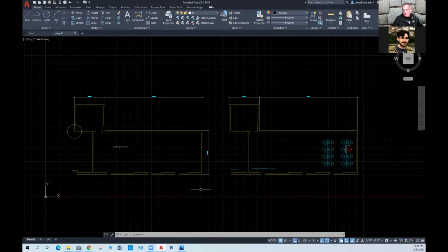And for that, the first thing that needs to happen is that you need to be in control of the global variables called LT scale, right? LT scale is a global variable, and you control the scale of all line types. And so if we type LT scale and then press enter, then we can set the LT scale to whatever scale we want.